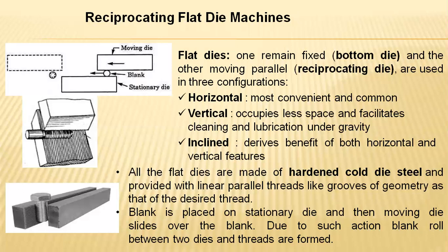Nominally, almost all these flat dies are made of hardened cold die steel, and they provide thread-like grooves of the geometry up to the desired thread limitations.